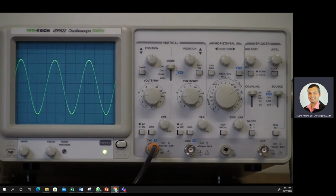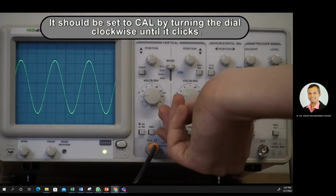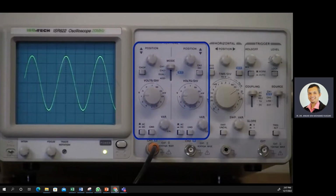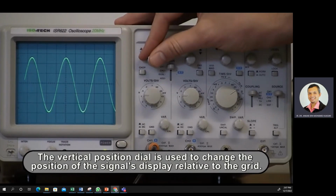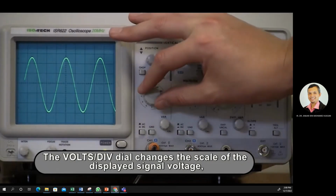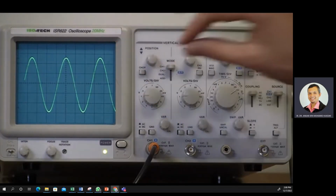So if we are using the source, it is channel one, so we set channel one. So in order to measure the voltage, we can use the vertical. Okay, this is how we can control the position of the vertical. This is for the range, maybe see the division, voltage per division.